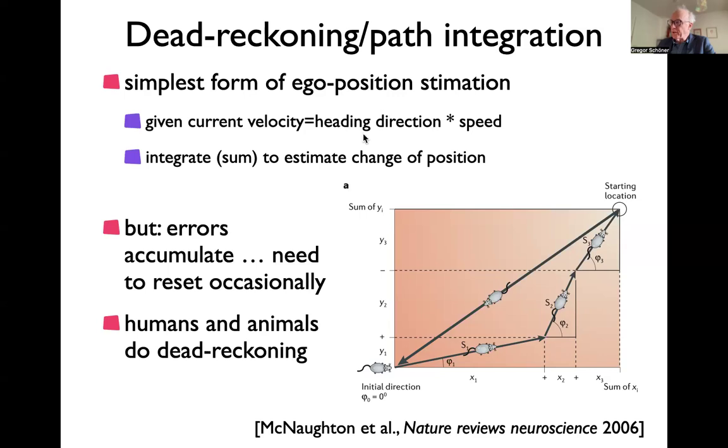In our robots, we actually don't have that, and you determine your heading by integrating your rate of change, your angular speed, to get an estimate of your current heading, which is already subject to uncertainty, the errors that accumulate. And in the literature for SLAM, there are interesting algorithms that try to get an estimate of your heading from visual flow, from seeing if you have any rotation in your visual flow, and that would give you some sensory information about where you're heading that's independent of your motor command.